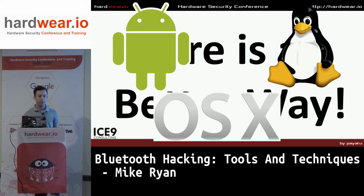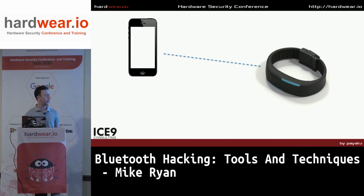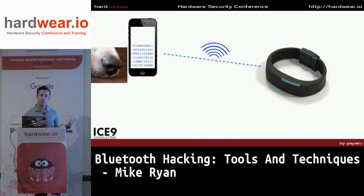How does that work? Well, let's go back to our model of the Bluetooth device. You've got your two devices, they're communicating via Bluetooth, and the sniffing approach is that we want to capture the data here as it's going over the air. Well, the data already exists on our smartphone, and this is a smartphone that's running an operating system. We have a lot of control over that device. So wouldn't it be great if we could sniff the data on the smartphone before it even goes over the air? And that's exactly what we're going to do.